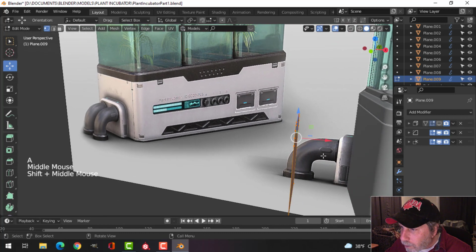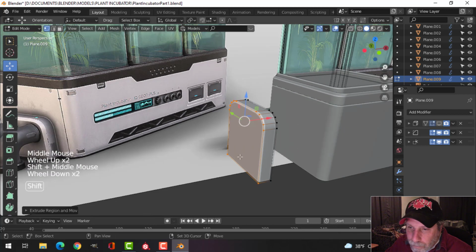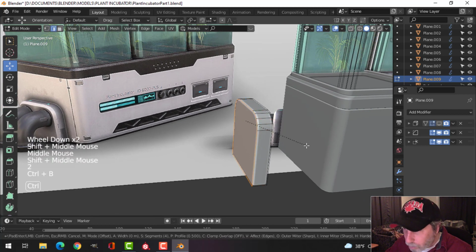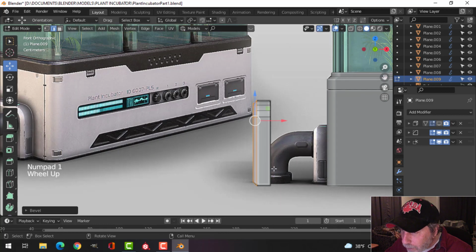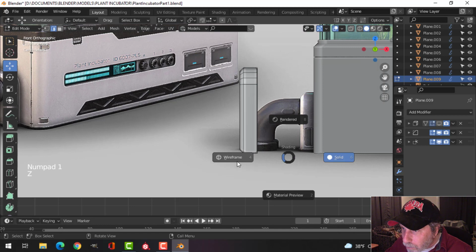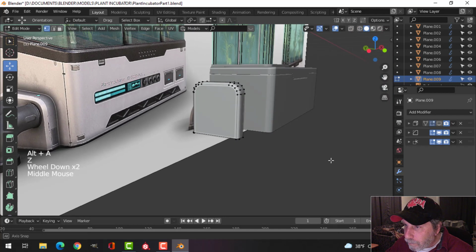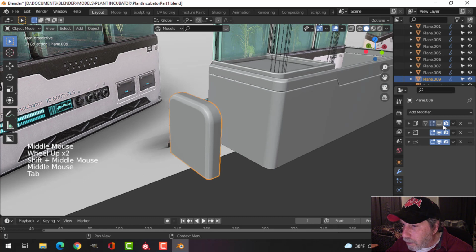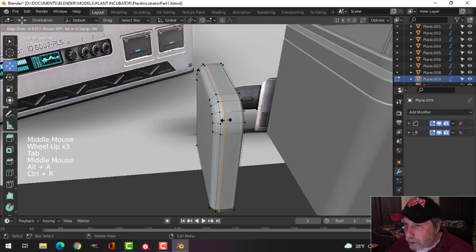Okay, we'll take the whole thing and we'll extrude it out a ways. And then let's just Control B, bevel back with one segment like that. You'll see that this part at the bottom sort of bends up. So what we'll do is I'll go into wireframe, select all that, and go S Z 0. I'll straighten it in the zero, in the Z, like that. I don't really need solidify on anymore, and let's put an edge loop in here.